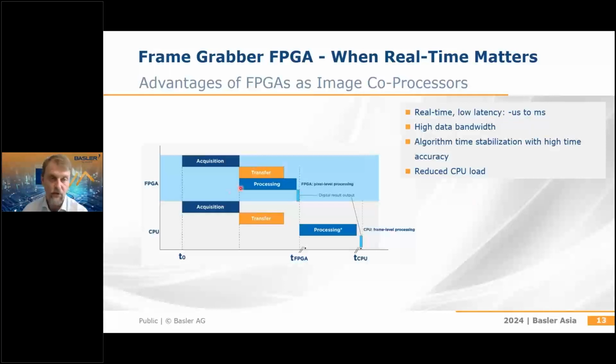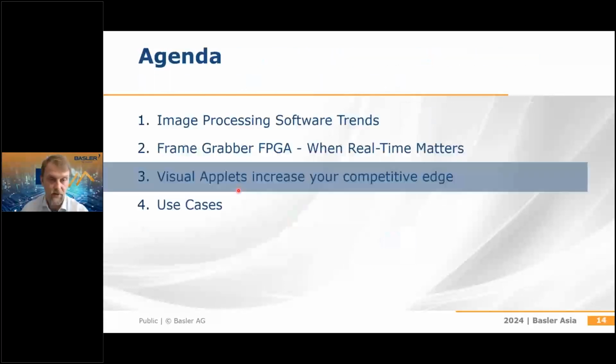When I'm talking about pre-processing, the pre-processing can also have a very strong focus on making the image acquisition very, very reliable. And the frame grabbers, for example the InnoFlex series I will show later on, have a system clock of 312.5 megahertz. This represents a timing granularity of 3.2 nanoseconds. So when you want to very precisely trigger a lot of cameras, synchronize these or do similar tasks, the FPGA, so the pre-processing device, can also take care of that part.